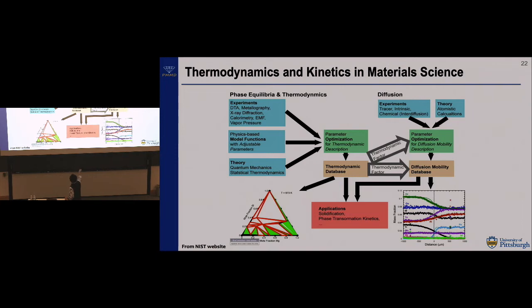After you have the thermodynamics, you actually have to consider diffusion. Remember, diffusion is not separate. So they always have some dynamic factor which reflects into the activity-related stuff. And then you have to pull from the thermodynamics. So if you have less accurate thermodynamics, you cannot get accurate diffusion at all, all right? So they are bound together.